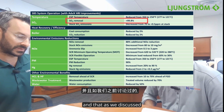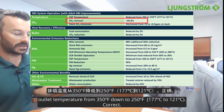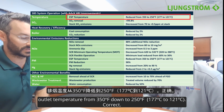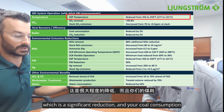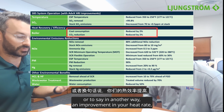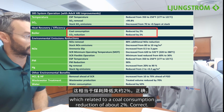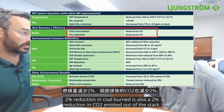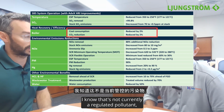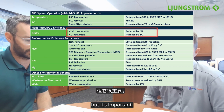And that, as we discussed earlier, has allowed you guys to reduce your gas outlet temperature from 350 degrees down to 250 degrees, which is a significant reduction in your coal consumption, or to say it another way, an improvement in your heat rate, which related to a coal consumption reduction of about 2%. Correct. 2% reduction in coal burn is also a 2% reduction in CO2 emitted out of the stack. I know that's not currently a regulated pollutant, but it's important to note moving forward.